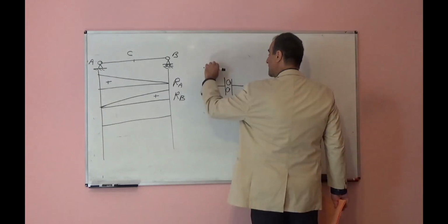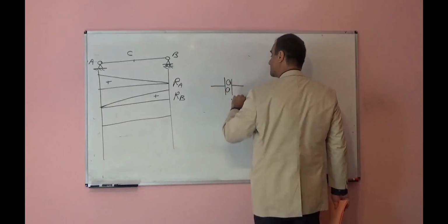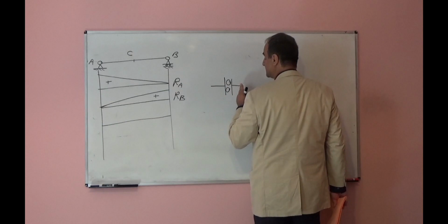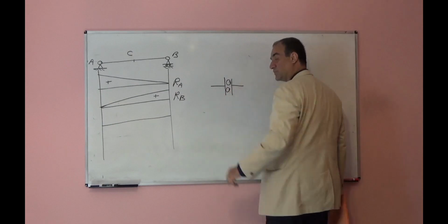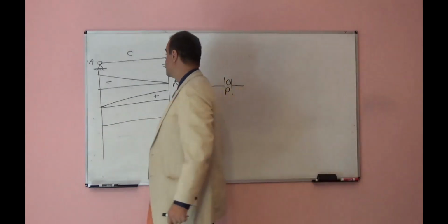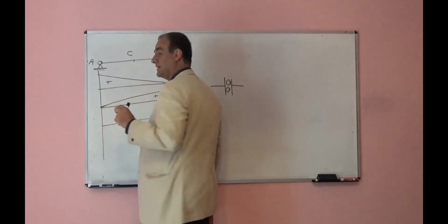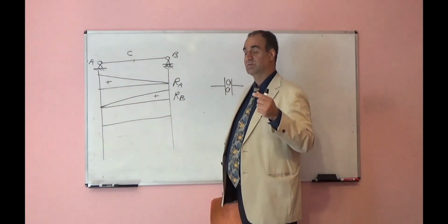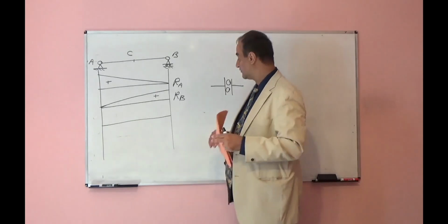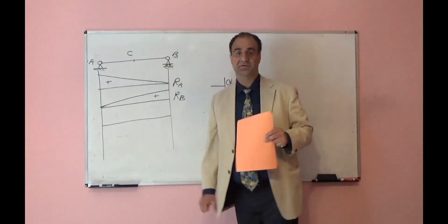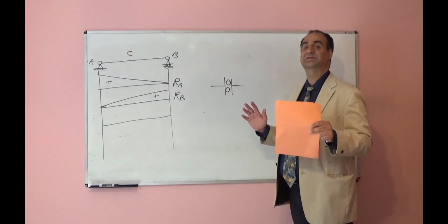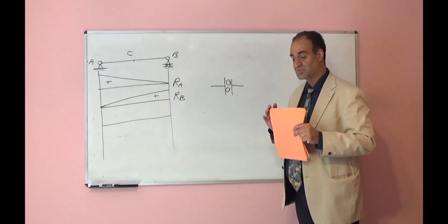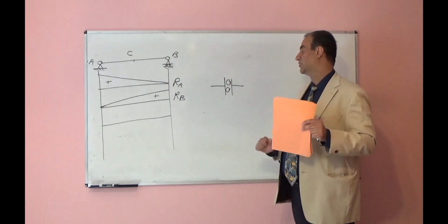You can take this up or down, you can take this up or down. So shear force will not transfer from left to right and right to left. So any location you want to draw influence line for shear, you will put this kind of node over there. So you will remove that restraint. You will remove shear force at that point.